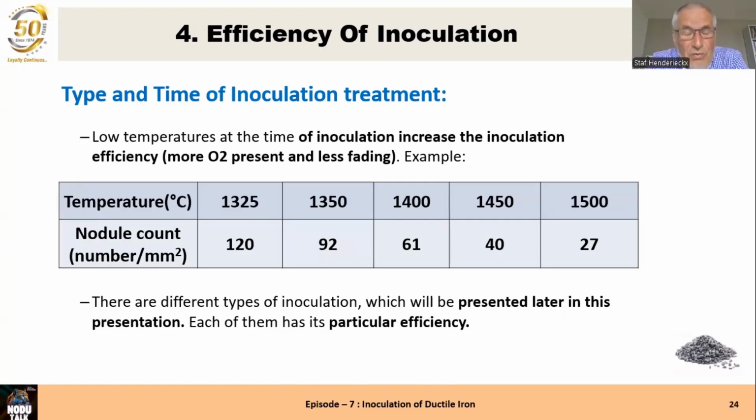That's due to the manager and the owner. If the temperature is too low, it can be that the casting has cold run. And everyone knows then if there is cold run, the guys in the furnace and doing the treatment have made a mistake, so they are blamed. If you see what the effect is, if you do an inoculation at different temperatures, it's just one of the